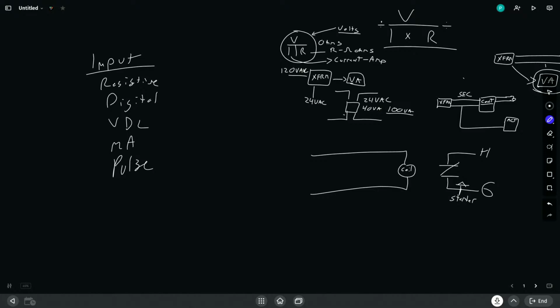Digital is typically an on-off state. This would be something like a contact closure where you are either sensing resistance or you're sending a 5-volt DC signal through this contact closure. As you sense that signal, the controller knows that the state has changed from either on, off, open, shut, etc. These are used for end switches, like on actuators and dampers. These are used for fan status with flow switches. These are also used as auxiliary inputs from safeties, like low temp safeties, etc.